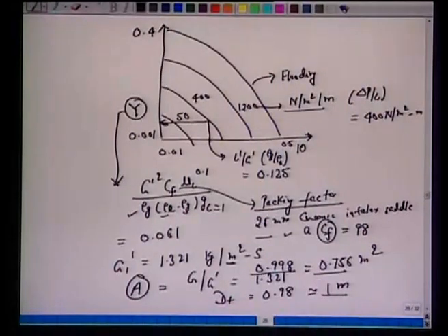Of course, this example we had on hydrodynamics. The idea is that we are not hitting this flooding curve. Some examples or problems could be rephrased in a different way. Knowing L prime, G prime, or the ratio of the two flow rates on the x axis, you may be asked to calculate the maximum gas flow rate for which we have this flooding. So all you are supposed to do is mark this point, hit this flooding curve, and you get G prime.